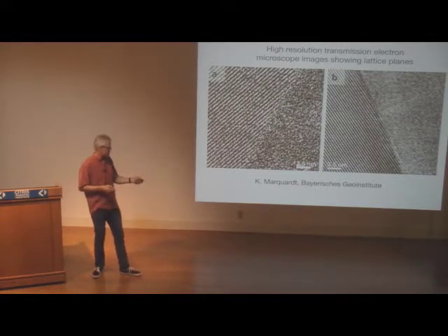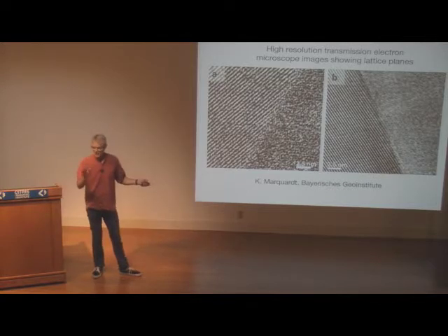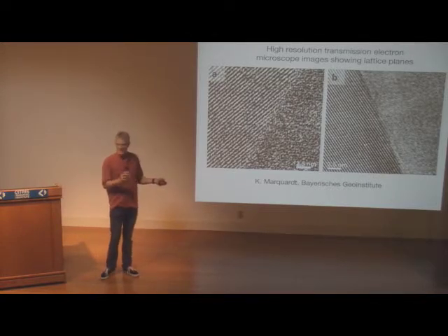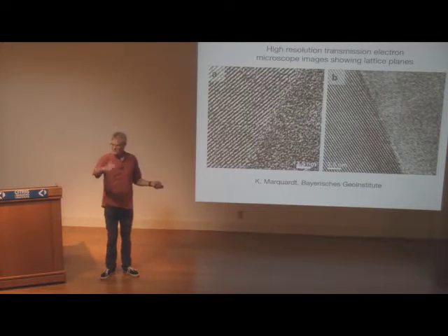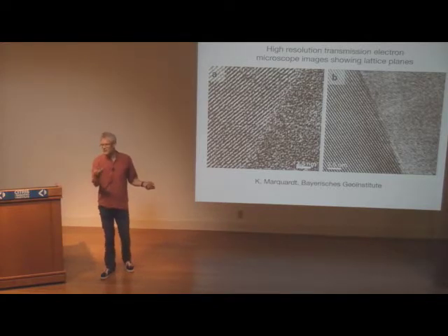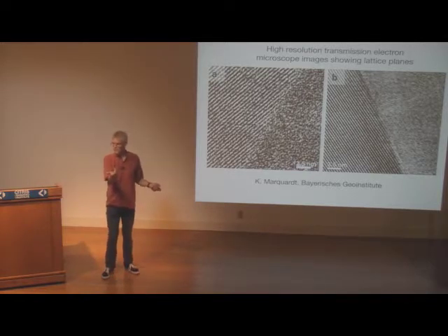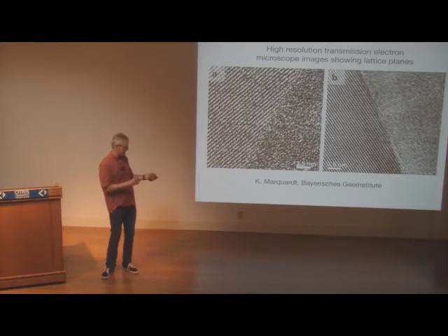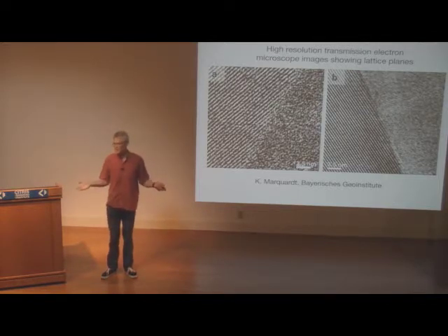So the relative orientations: basically, you have the orientation in 3-dimensional space of the crystal lattices, and then you have the relative grain boundary plane orientation. So you have 5 parameters essentially that describe your grain boundary plane: how to rotate one crystal onto the other, and then the orientation of the grain boundary plane. All of that you have to take into account, and then it turns out, not that surprisingly, that you have different grain boundary geometries.